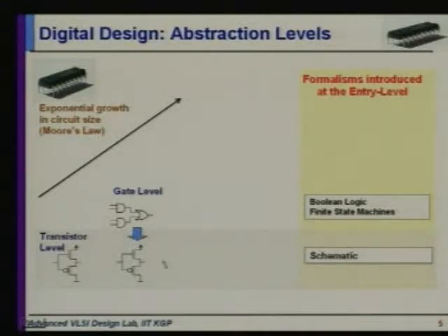At the lowest layer we have schematic. Now, what is a schematic? A schematic actually specifies the gate, drain and source connectivities of the different transistors, which is connected to what, and it also tells you the geometries of these transistors, what are the width and height of these transistors. When you go one layer up, you are now in the Boolean logic domain.